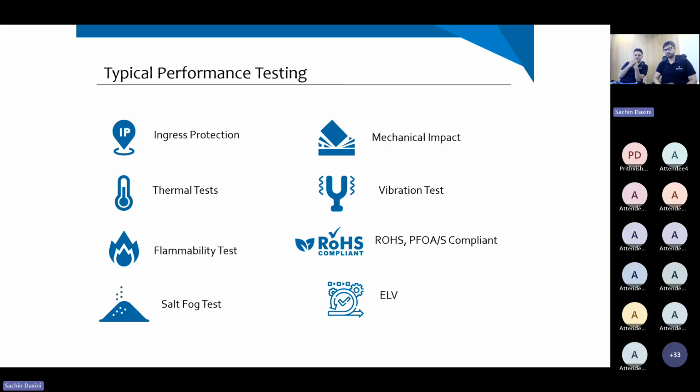Vibration test is performed for structural integrity, followed by IPX7. We do perform IPX7 test after vibration test so that we ensure that the performance of the vent is retained. So there is no ingress protection compromised after vibration. From environmental perspective, we do perform RoHS and ELV testing. So these two tests are from the environmental perspective. All our products are tested for these environmental tests also.